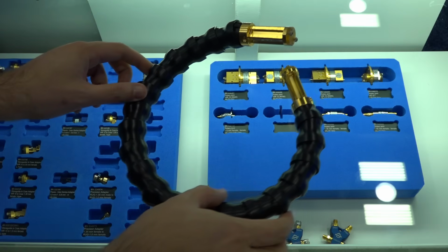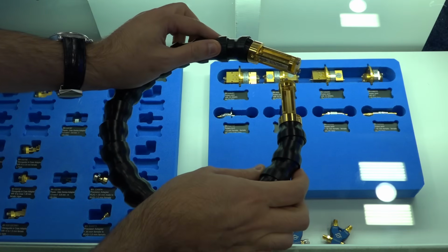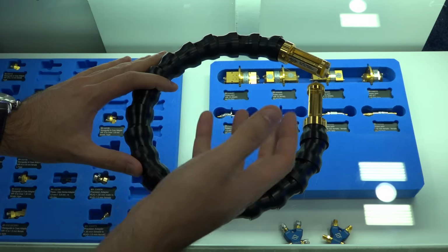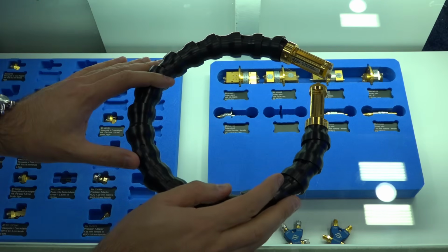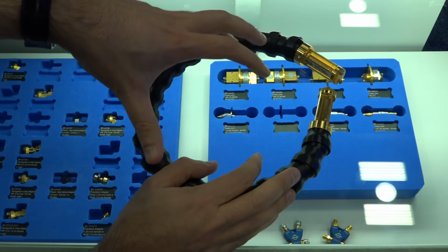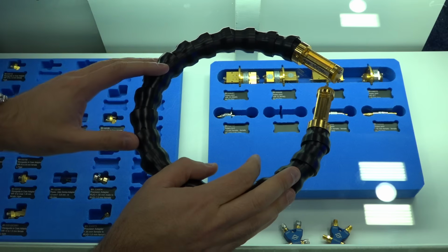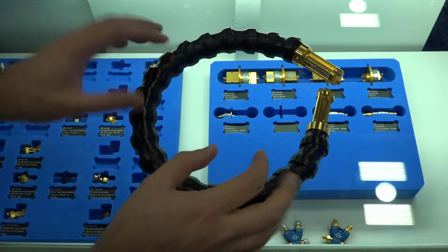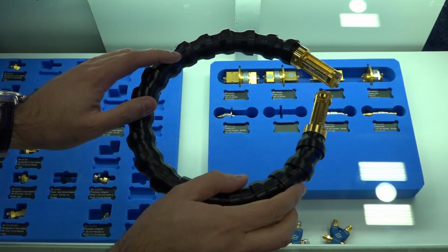So here I have a very unusual flexible waveguide. Now traditionally flexible waveguides are of course useful when you want to connect things that have an unusual interface or things that are potentially moving or you're setting up. But this type of flexible waveguide typically has a lot of loss, and that loss obviously eats into the dynamic range of the measurement you're trying to do. And there's a certain rigidity and a certain lifetime that they may have.